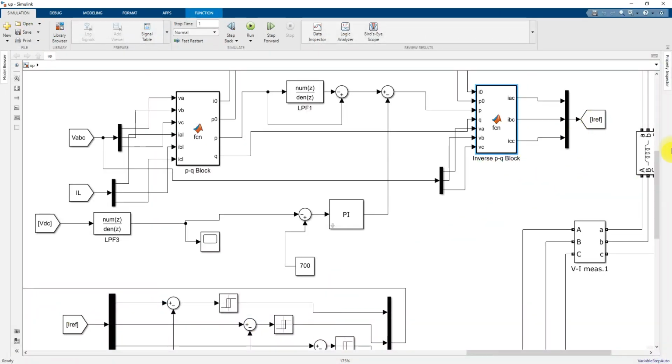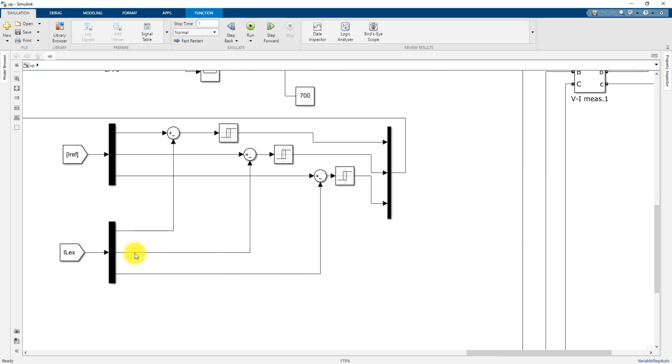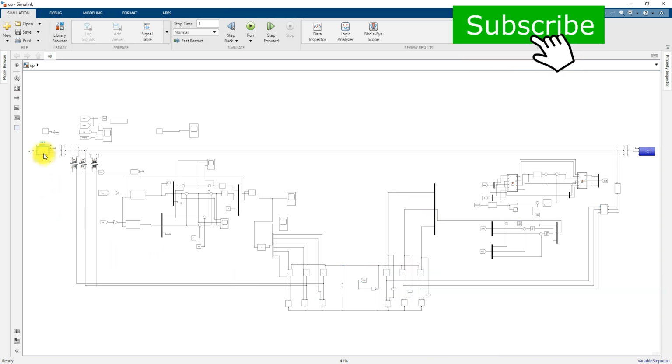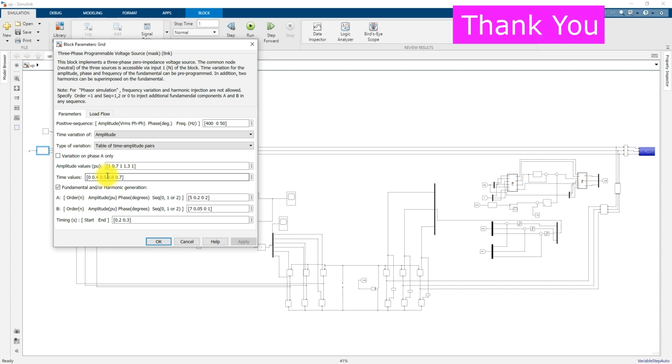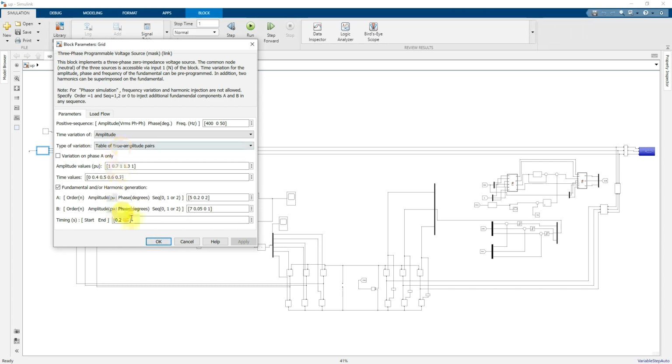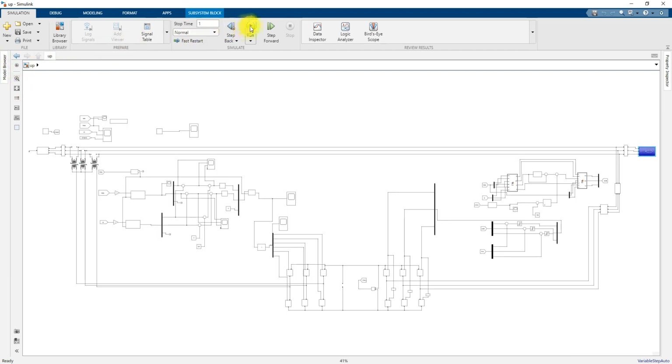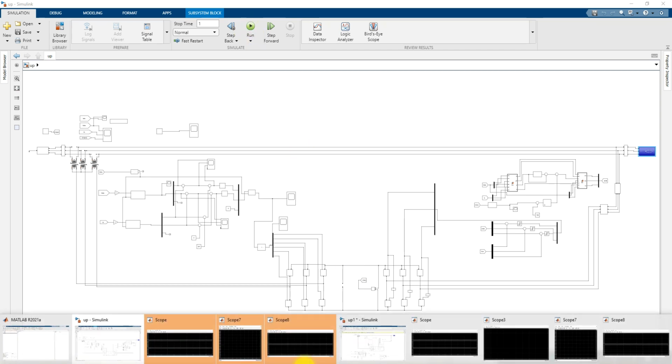Okay, and then this reference current is compared with the current of this shunt active filter, processed by the hysteresis controller, and then it is going to control the voltage source inverter of this shunt power filter. So here we apply DQ0 for the series active filter and the PQ control concept for the shunt active filter. Here also we are taking the same operating condition for the source side as well as the load side. We are having a nonlinear load. So the first time you want to simulate this model, you have to check the results.